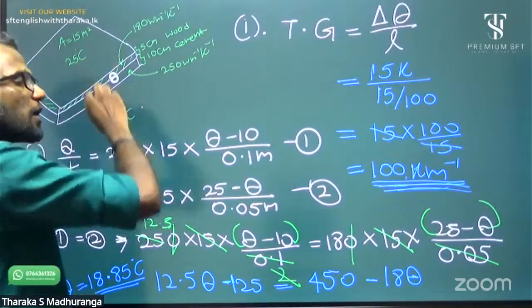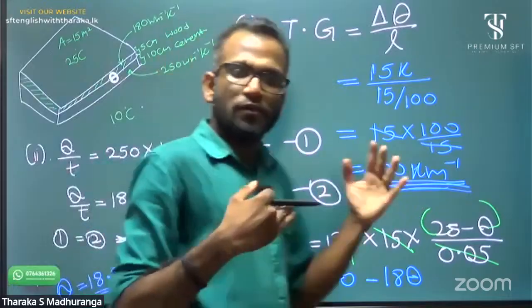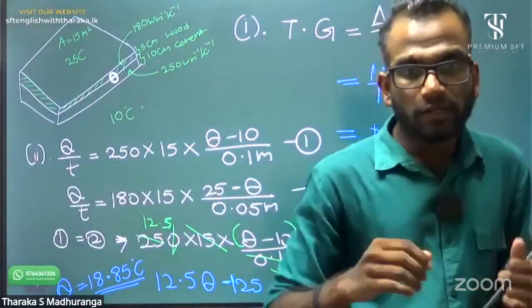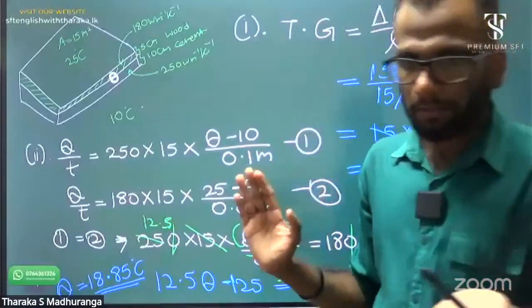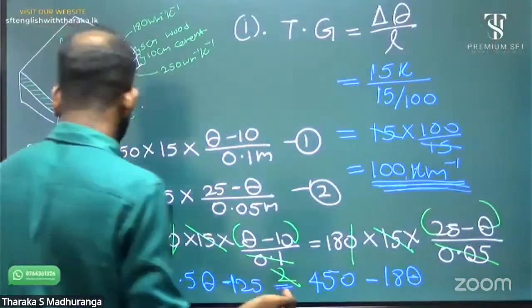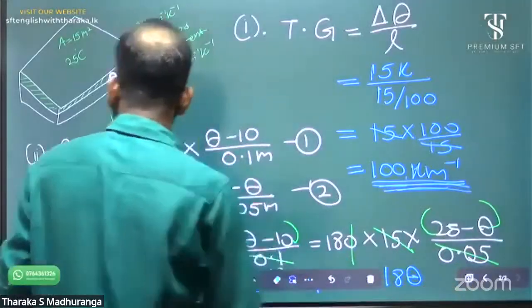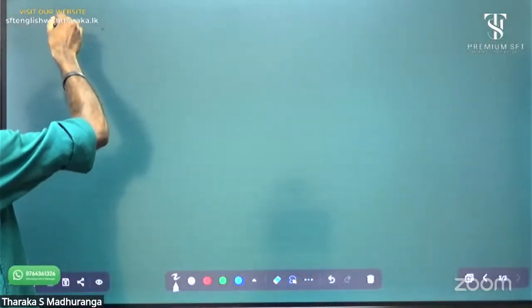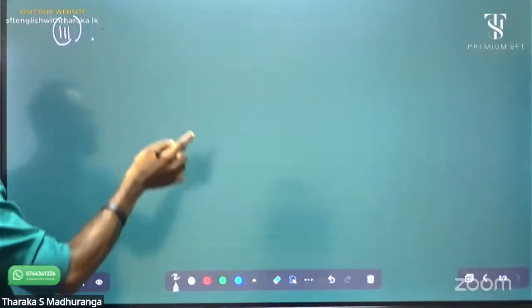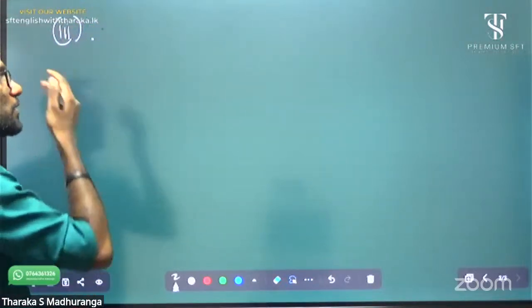Therefore the thermal conduction rate for both walls is the same, though thermal conductivity differs. Now you can get the thermal conduction rate for any wall because you already know the intersurface temperature.